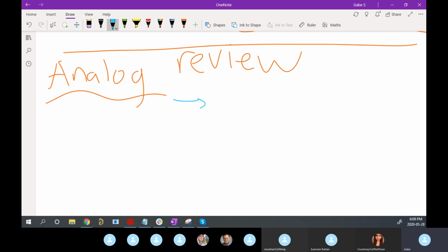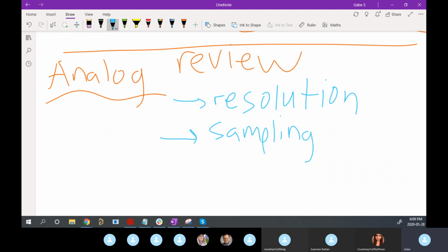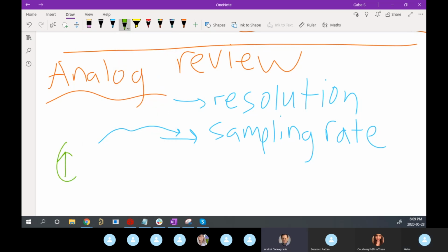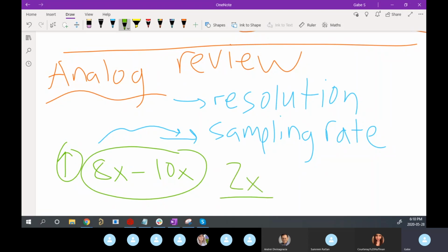So what did we talk about? Do you guys want to remind me? It's something like resolution, right? Resolution. Talked about sampling speed. Sampling rate, maybe, is a better word. And what was the rule we talked about for sampling rate? The higher, the better. Like 2 times more is the minimum. Yeah, 8 to 10 is good. 2x is the quote-unquote rule, but you're really not going to get a good representation of your signal that way. You want to have at least 8 to 10.